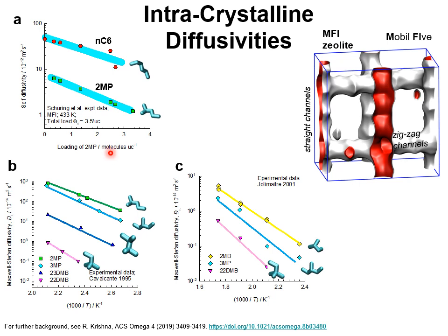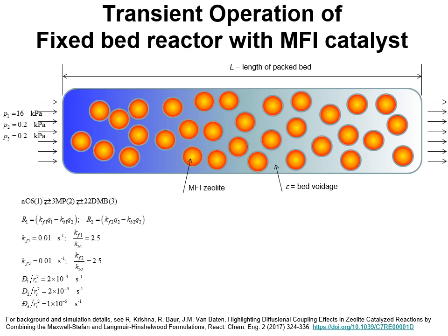And in this reactor, we use MFI catalyst. In order to demonstrate the technological benefits of the synergy between adsorption and diffusion, we simulate the transient operation of a fixed bed reactor packed with MFI catalyst, carrying out the isomerization reaction.